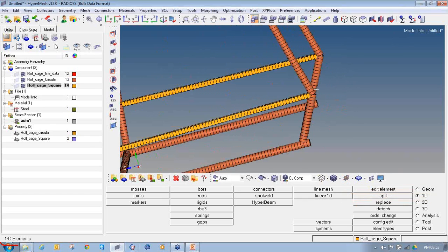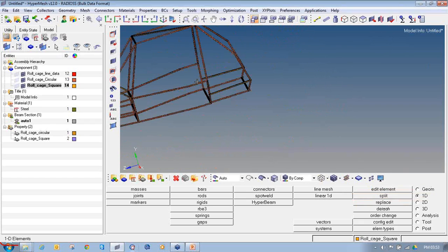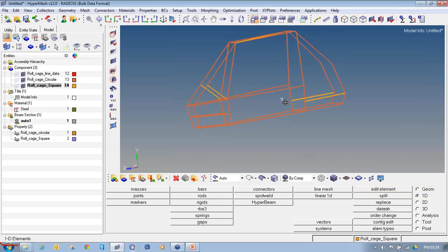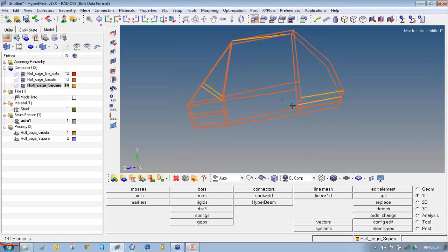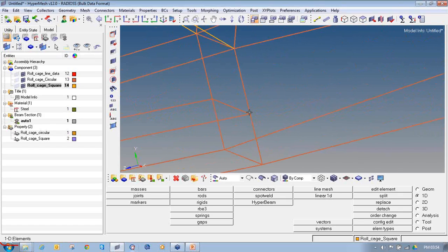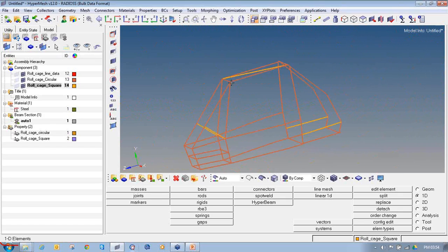So you can also check it once. So all are showing in a 3D representation. Once the connectivity and resolution is checked, we'll also perform a free run to see all the members should be connected. To make sure that all the members are connected properly, I will perform a free run, because I'll show you one example where it may be possible the elements' connectivity may differ.